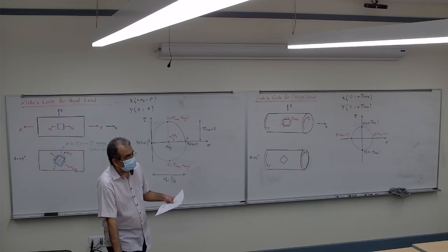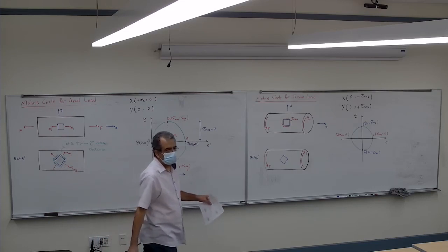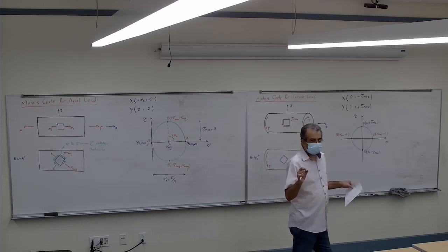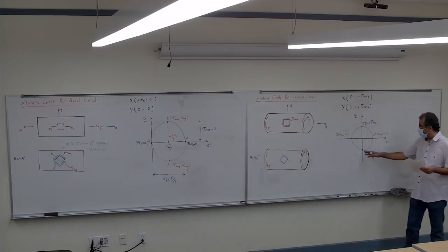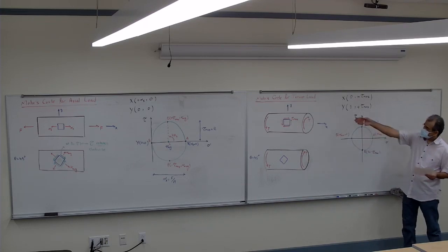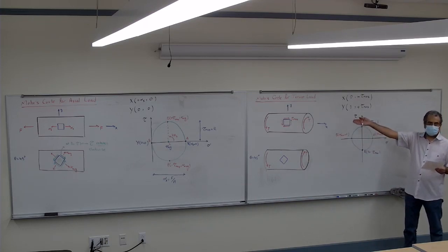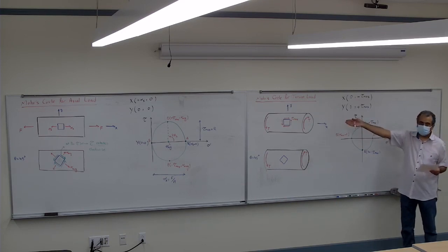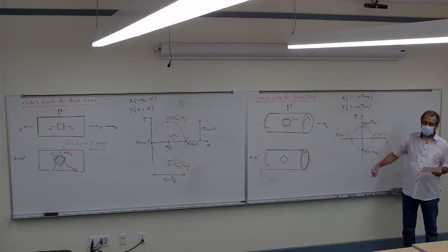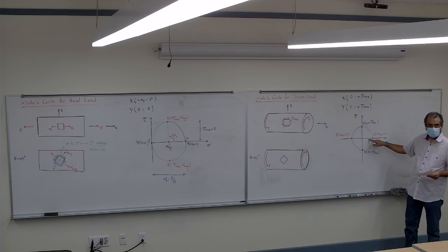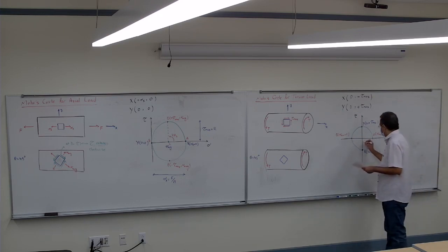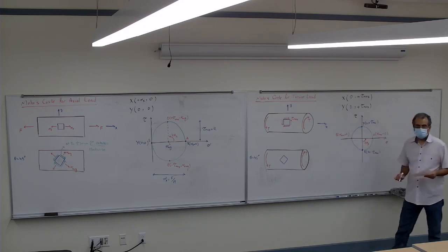Theta is 0, because we're already at the tau. 2 theta S is, so the theta S is basically there, so 2 theta is 0, so theta is 0, so at 0 you have the tau max. The 2 theta P is this, from the point X going to there, so it's going to be 90 degrees, from here to here it's going to be 2 theta P.